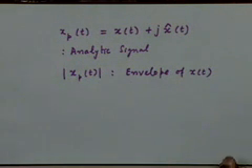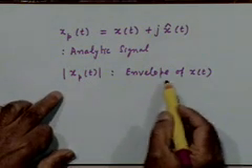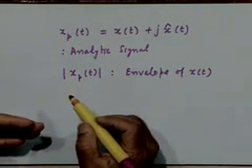Now the concept of envelope I tried to give you by taking a specific kind of signal, for example when a low pass signal m of t multiplies a carrier kind of signal cosine omega naught t, and we found that the modulus of m of t defines the envelope of this signal m of t cosine omega naught t, right. However, not all signals may be of this kind, that is a low pass signal multiplied by a band pass signal, right. Whereas if you look at this definition of the envelope as I have defined here, this is valid for all kinds of signals. So in that sense, this concept of envelope is a generalization of the physical concept that we discussed yesterday.